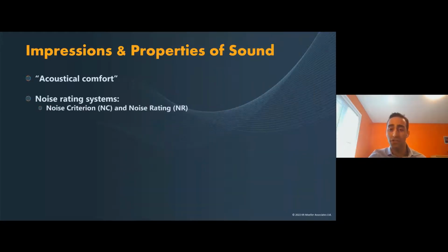Interestingly, the same conclusions are identified in investigations supporting the development of noise rating systems, such as the noise criterion and the noise rating. These rating systems apply a reference contour, which is approximately -5 decibels per full octave band, to measurements of the existing ambient acoustic conditions of a space. However, these methodologies assume the environment is spectrally neutral.